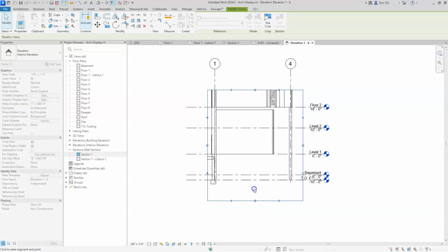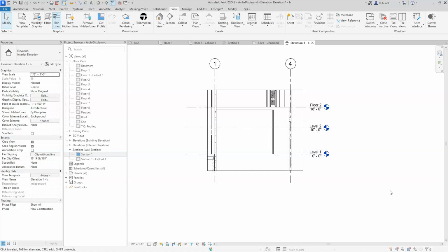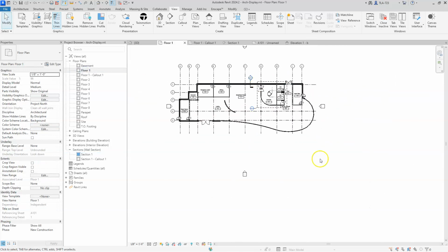So that's another key thing in Revit, is the views don't always come in exactly the size or the view depth that you want, so you will have to make some adjustments, and then you'll also need to adjust the detail level and possibly the scale. So if we had already designed the kitchen and placed all the cabinets and the appliances and things like that, they would all be showing up in this view, but we didn't do any of that yet, so kind of boring to look at this point, but that certainly would populate with anything that we added to that floor plan as we did it. Let's go ahead and take a quick look at the exterior elevations then.